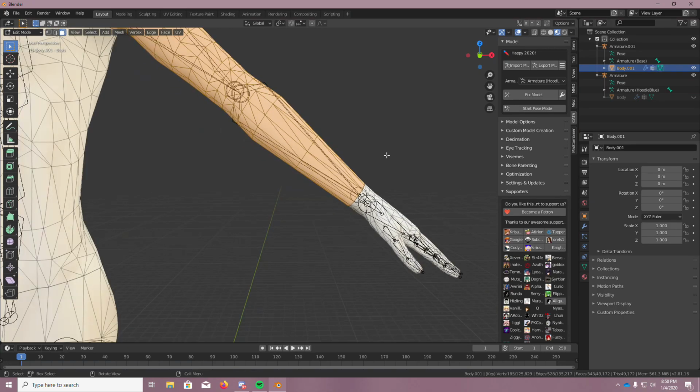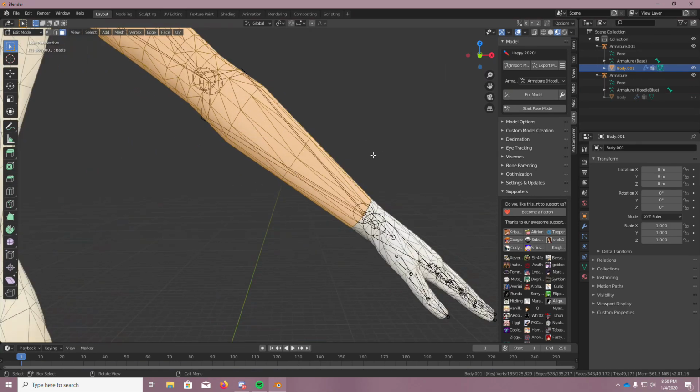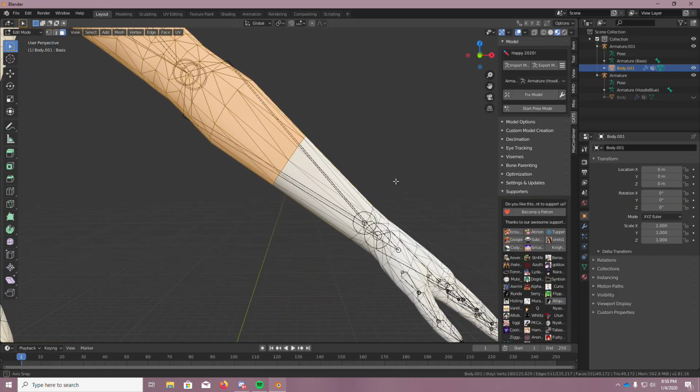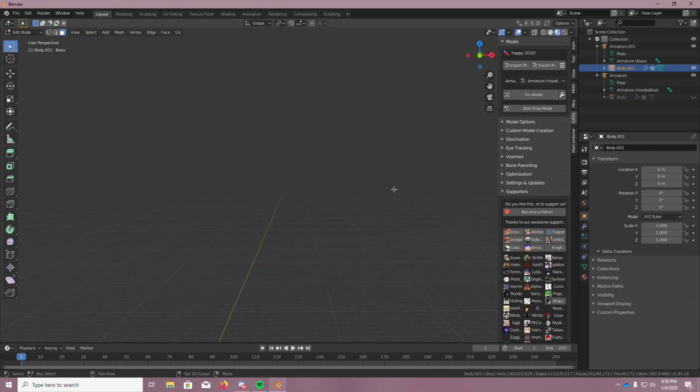So we're gonna go ahead and hide, just Control Z, and we're gonna go ahead and press C. Okay, no, C. And we're gonna deselect these faces. Basically, it's a select tool. And then from there you just hold Shift, and then you click on them to deselect them. So then we go ahead and exit out, press Escape, and then we're gonna go to the other side.